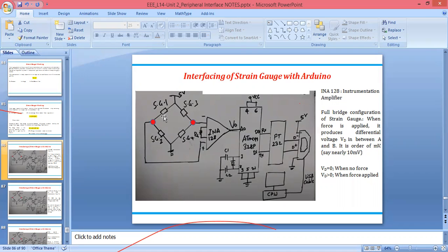So this Wheatstone bridge is used to measure the value of unknown electrical resistor by balancing two legs of electrical circuit. So among the resistors here, there will be one potentiometer, rheostat, we can say rheostat or a potentiometer. So we can adjust the value of remaining resistor by using that potentiometer.